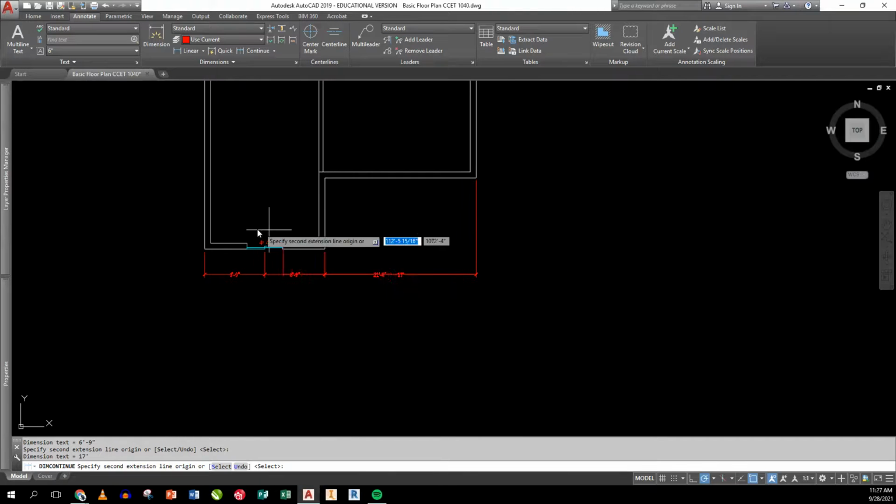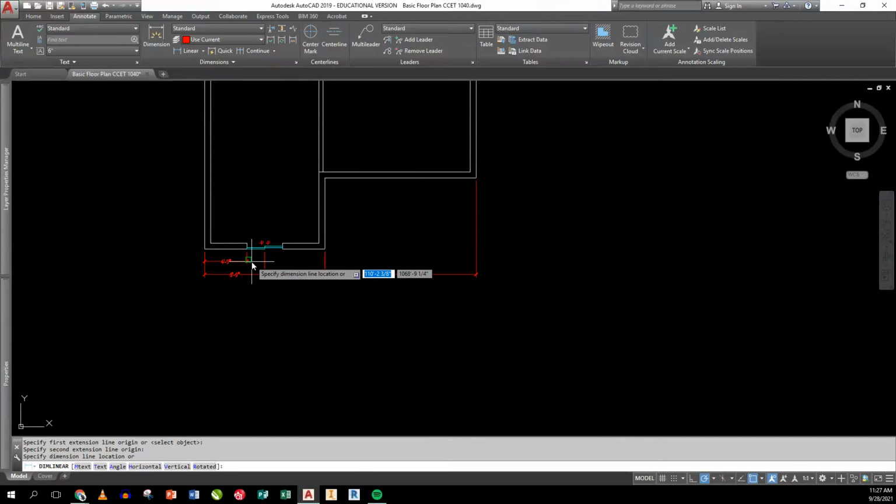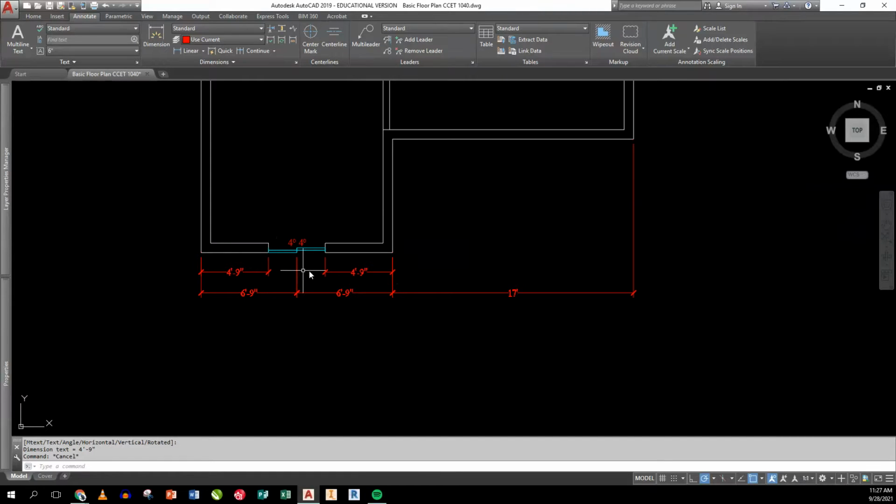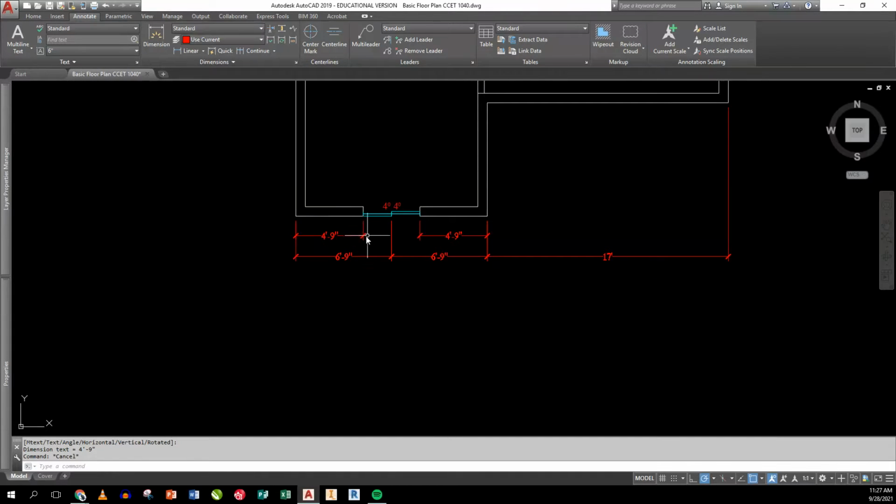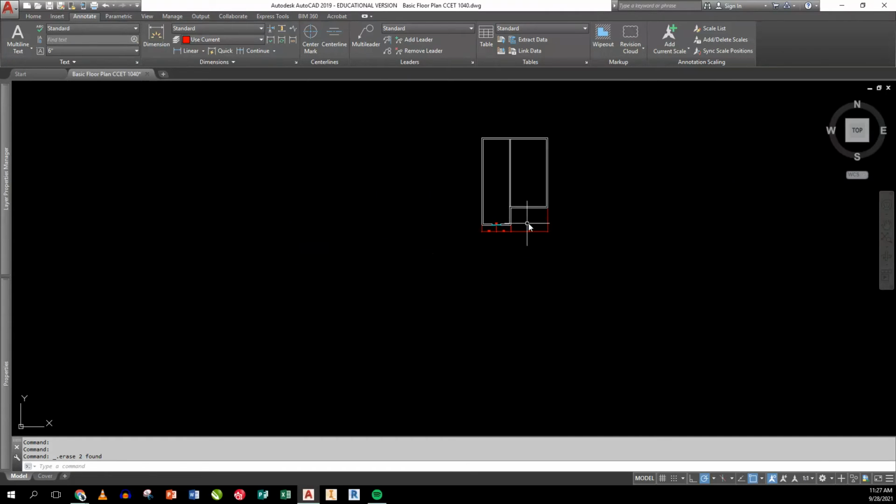Now, if I have any openings, I measure the opening. Now, here's the fun part with this. Sometimes you want to do the dimension such that it just measures where the opening falls, so that you can know for brick layers and things like that. I do it to centers of windows because I don't know what manufacturer window each contractor is using. When they see the window and they know the center, they can get their frames to match and stick them right in their foundation. So that's where we're at with it.